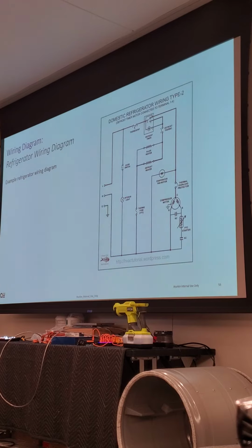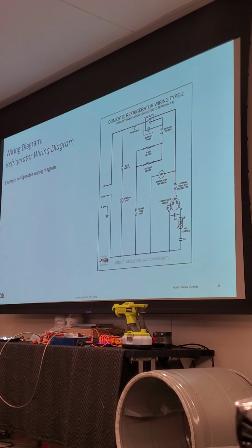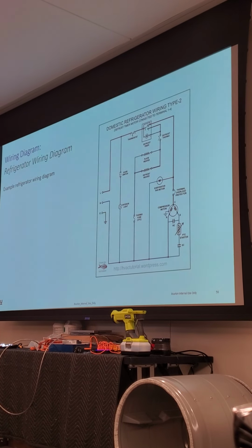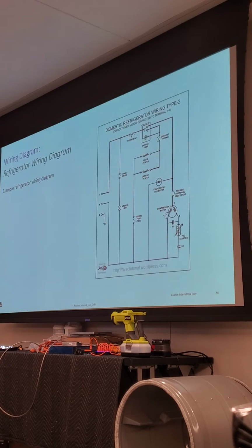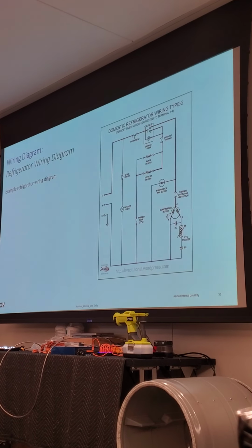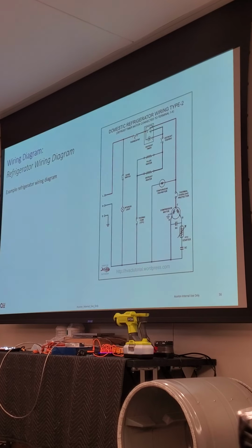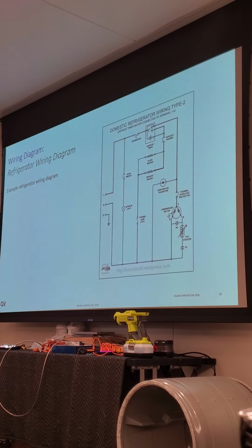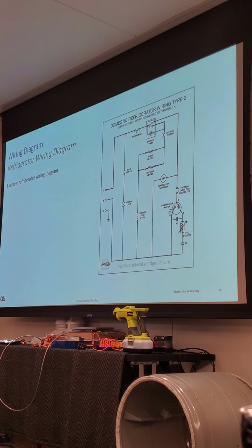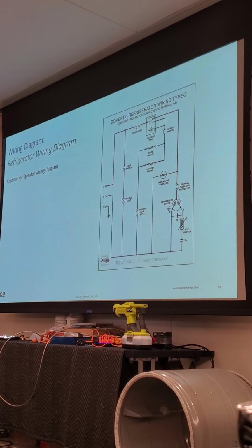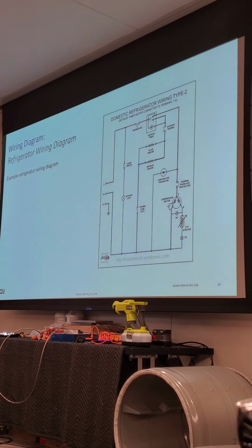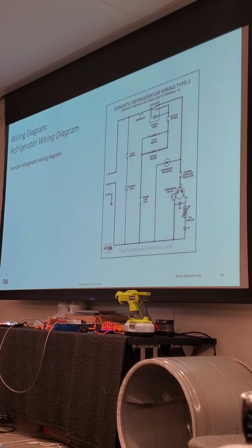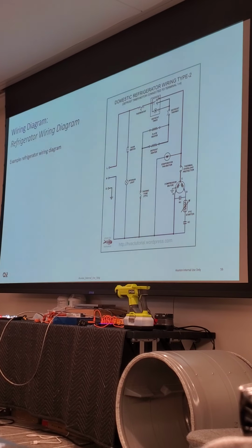Okay? Like for Samsung, door openings, the amount of time the refrigerator and everything's been running, all this stuff goes into it. And then that sensor in there that's actually attached to the evaporator, which is a temp sensor or a thermal fuse, okay, is going to tell the heater to come on. What the bimetal in those do, it's actually another temp sensor with a resistor in there. All it's going to tell it to do is send a signal back to the board to tell it I'm done defrosting. It doesn't open and cut the power. That's all done by the circuitry in the board. So that makes it operate just a little bit differently.